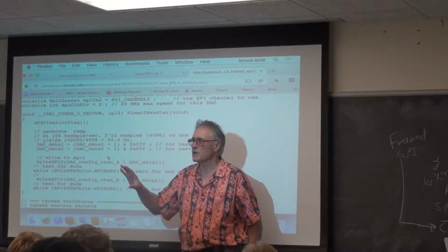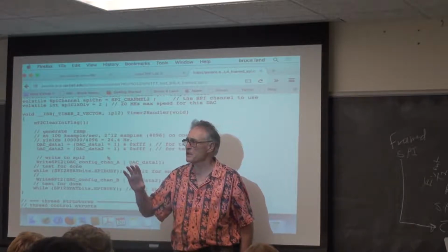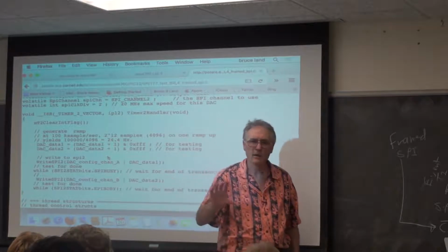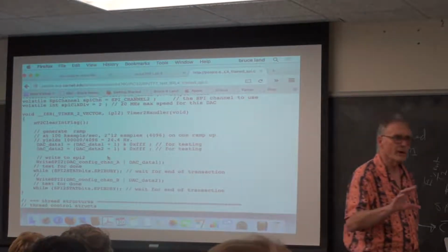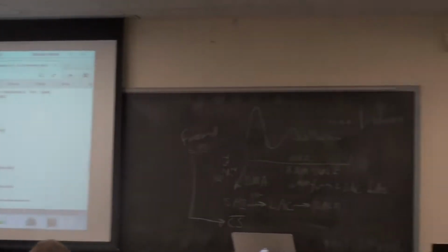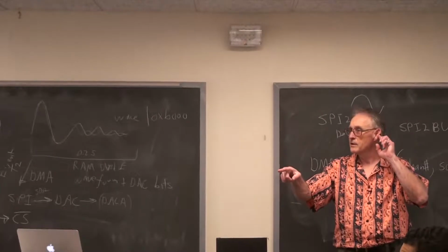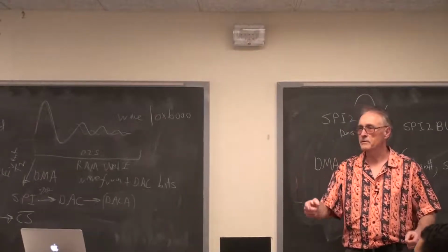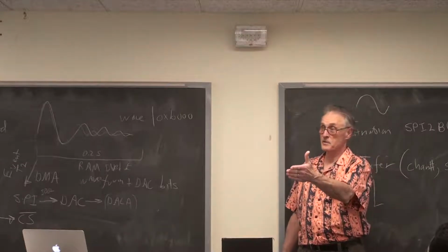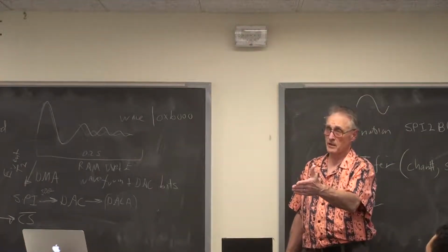What's missing compared to the interrupt service routine you have just been writing? What's different about that? It has two channels rather than one channel because I was doing both channels. I heard the magic word. Chip select. There is no chip select because it's framed. So the chip select is automagic.